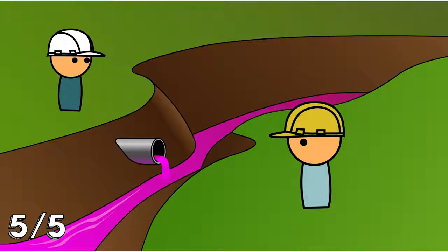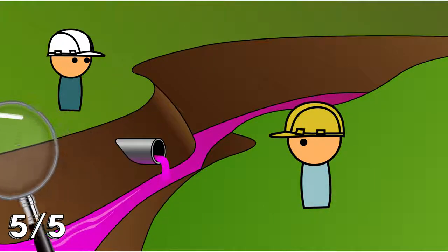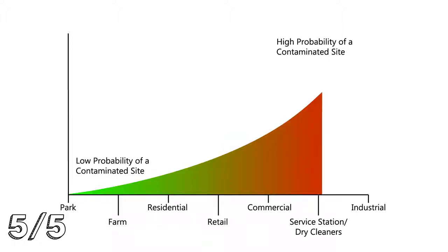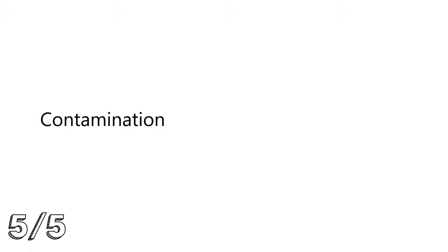If contamination is suspected, an environmental investigation should be conducted before proceeding with the green stormwater infrastructure design and construction. One of the objectives of the investigation is to identify the location and size of the area where contaminant concentrations represent an unacceptable risk. Contamination at a site does not necessarily exclude stormwater management practices that include infiltration. There may be instances where stormwater management approaches that can include infiltration may be appropriate on a site with contamination.